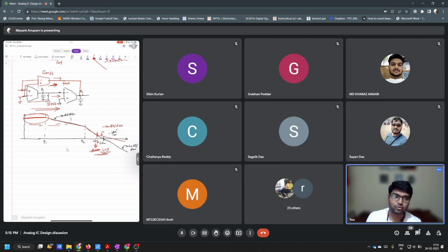But at very low frequencies, slow and fast we cannot differentiate, right? How can you differentiate between slow and fast? Will you be able to differentiate when one path is slow and one path is fast? When you apply high frequency signals, right? For a DC, there is no meaning of slow or fast. At every point in time, it is the same. The DC level is never changing, so you cannot say whether it is delayed or not. So the slow and fast comparison can only be done when you have a reference frequency, and that frequency should be high enough to make that distinction. That is why this fast and slow path distinction comes only at high frequencies.